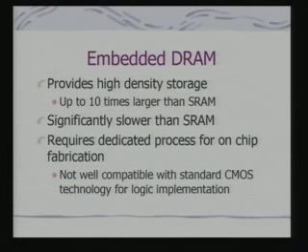So, that is the basic intuition behind designing burst mode access to these DRAMs. Obviously, when we have embedded DRAM going onto SoCs, it is primarily for providing high density storage, although it is significantly slower than SRAM. Another difficulty is that it requires a dedicated process for on-chip fabrication, because it is not really compatible with the standard CMOS technology which goes into fabrication of your logic modules, which are your processors and peripheral controllers.